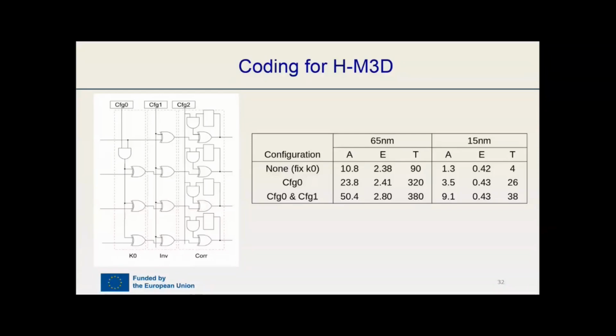Or we want to develop another hardware that, let's say, has all the possibilities, or we just want to restrict ourselves to the possibility of sending the normal data and just to allow the configuration zero to have a case zero coding. With that, fundamentally, you can see that you can get a trade-off between the area overhead in the encoder, the energy of the encoding process, but then the total amount of the reduction in transition activity that we can get.